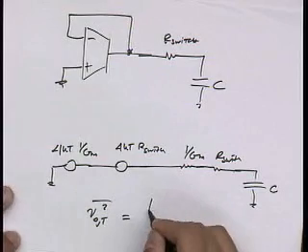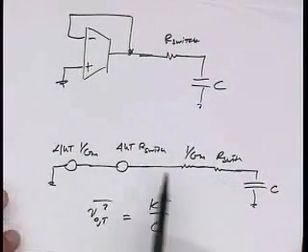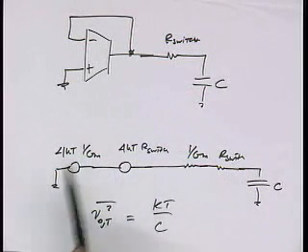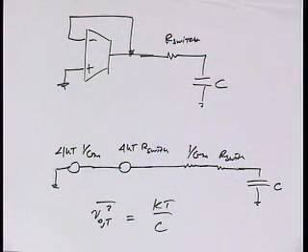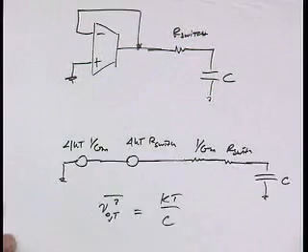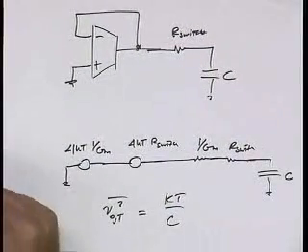Yeah, everybody knows the answer now because it's just KT over C, because the amount of noise is equal to the amount of resistance I have. So the noise bandwidth, in effect, compensates perfectly for the amount of noise being generated. Okay? So that's actually another good reason to use an OTA, because I'm going to be designing switched capacitor circuits anyway. What I really care about is this KT over C noise. And if I use a buffer, I mess things up.